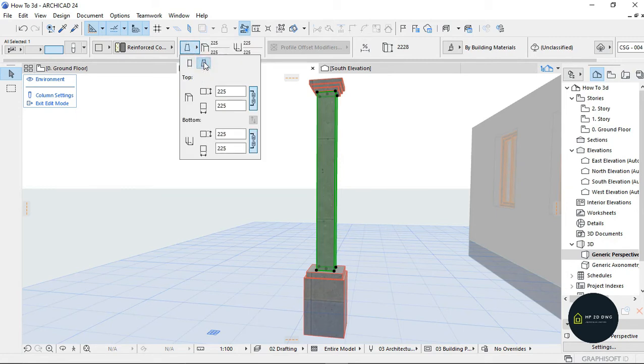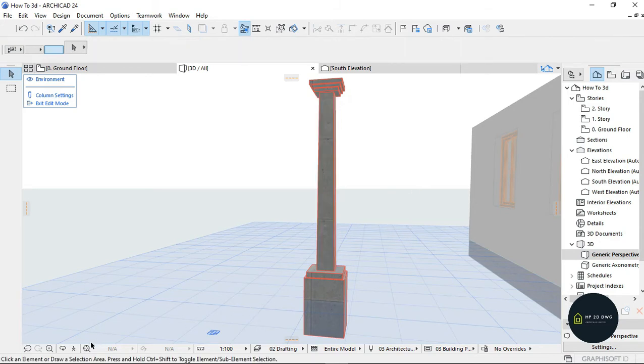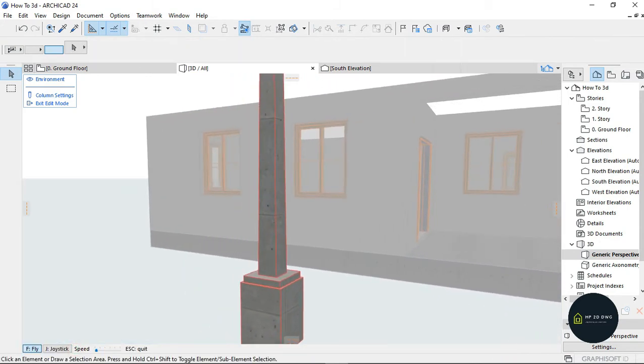Okay, select this, and this side and this side mean the upper part of the column, and this side means the bottom, as you can see, top, bottom. So you want to change this to be, let me say, I'm just going to use 180. So it changes automatically because this link dimensions is enabled, and I press escape. So automatically you can see that it's